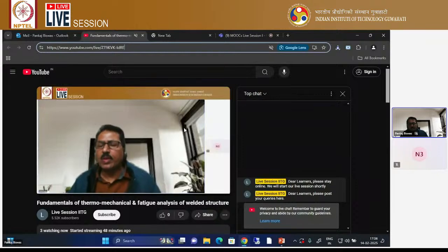In this course I have discussed different types of fatigue analysis approaches which are commonly used in welded joint analysis. Here I have covered the LEFM approach, linear elastic fracture mechanics approach. I have also covered some very important global and local fatigue analysis approaches, which are called the hot spot stress method, then the nominal stress approach.